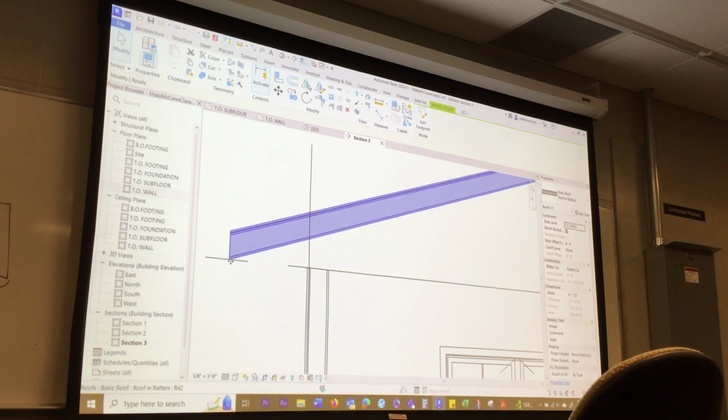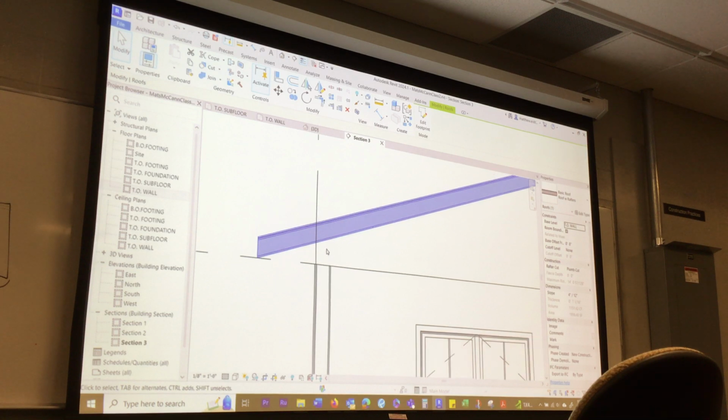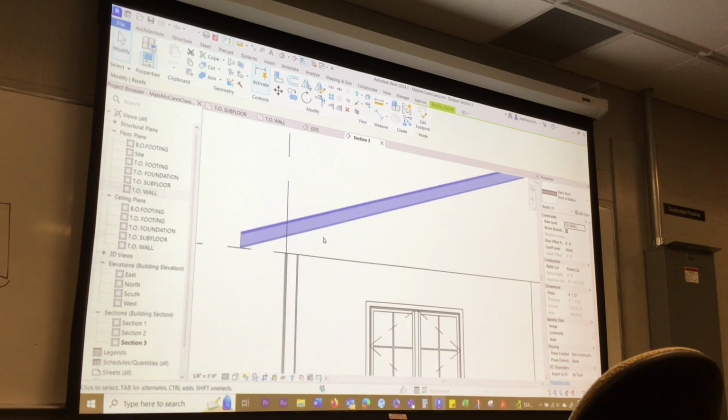This is important from a building science standpoint, because this is a huge leakage spot for insulation on homes, right here. Another way to combat it, when you put an exterior insulation system on the wall, is to run it right up the heel face too, to within an inch underneath that sheathing, so you get airflow over top. We used to build this in the lab, and it was a lot of fun putting the trusses on. I miss it, but this is gonna simulate it.